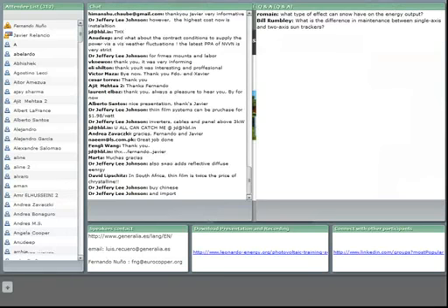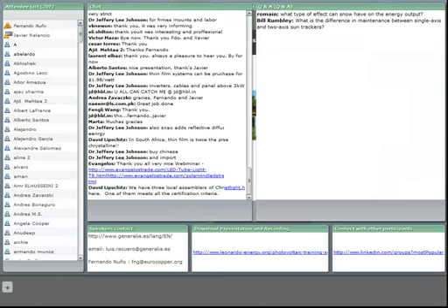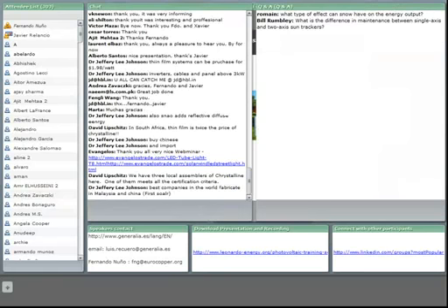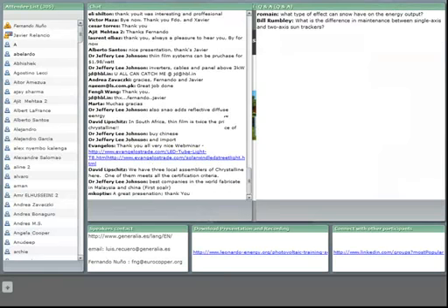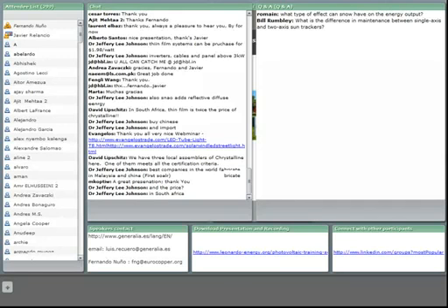Well, I have selected a new question from Bill Rumbley, who is asking what is the difference in maintenance between single axis and two axis sun trackers. Well, the main difference will be that in two axis sun trackers we normally have two motors and we also have two sensors. As we have said during this webinar, the main maintenance tasks to be done for the sun trackers are the lubricating of the motors and the maintenance of the sensors.